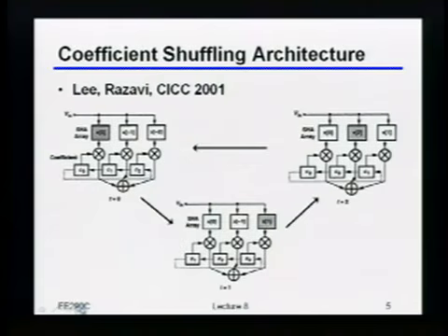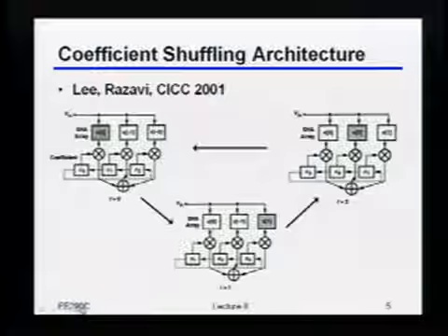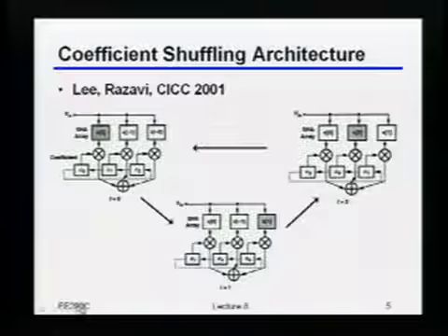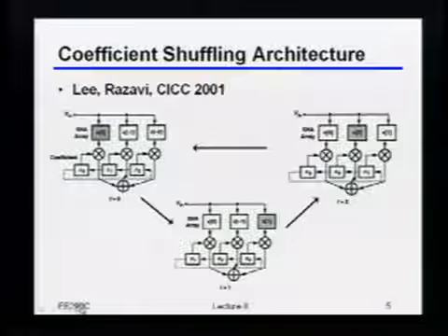And those analog delays basically end up being some sort of sample and hold circuit, which then end up causing either distortion or power because you have to make sure that your noise is sufficiently small, and so on and so forth. So what we then started talking about was other ways you could build FIR filters in the analog receive domain. You could do it on the transmitter too, of course, but it doesn't really make too much sense. Where basically you just try to avoid these long sort of analog delay chains.